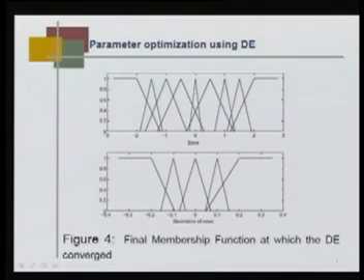So, doing this, when we did the optimization, you see that I have a variable base length. The base lengths were decided by differential evolution. My error is fuzzy partitioned into 9 linguistic variables: 1, 2, 3, 4, 5, 6, 7, 8, 9. The peaks are fixed, only the base, you see that this is the base that is obtained from the differential evolution, like for this particular one.